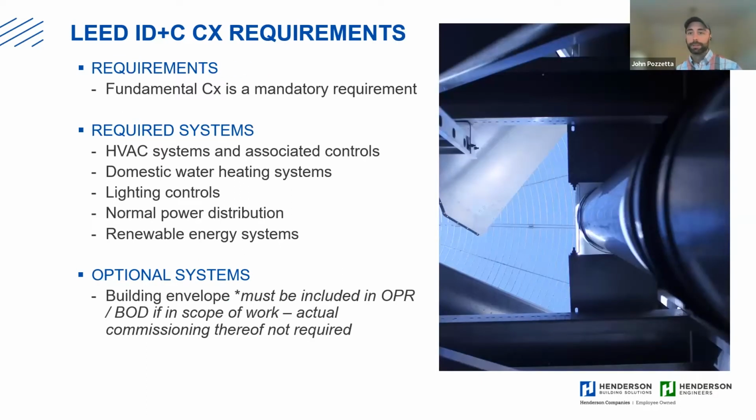Like LEED BD+C, which we also talked about recently, fundamental commissioning is a mandatory requirement for LEED ID+C. We're going to be commissioning the energy consuming and energy producing systems if we have renewables on site. We may also optionally look at the building envelope as it relates to the interior boundaries, although it's less of a requirement than it is with LEED BD+C.